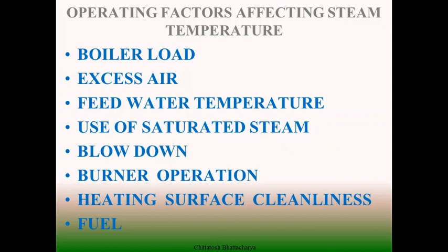Then how the saturated steam is generated in terms of quantity and dryness is also important, and how much blowdown is given to control the quality of steam is also part of the quantity of steaming, because generally 2 to 4% blowdown is essential, but if blowdown is more, naturally generation of steam is hampered in terms of requirement, because not all the feed water flowing is going to generate steam, and there is loss of water from the system, and we require makeup water to fill the gap between steam generated and water used for that.